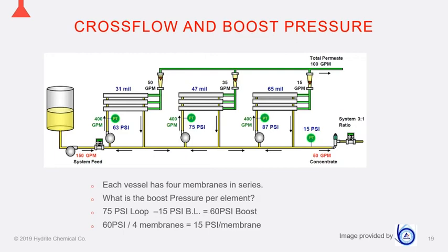If it's below the range that we recommend, then we would get that lazy river flow. We would probably see premature fouling in production. And then also we would probably have some issues with CIP because we wouldn't have that scrubbing action. If the pressure differential is out of range or too high, we can have some compaction and crushing issues on the membrane itself.